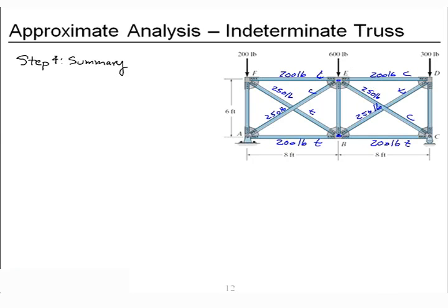My vertical members, we had 350 pounds, that's a 50, compression here at AF. 300 pounds compression here in member BE. 450 pounds compression here at member CD. So now we're ready for step 5. Let's go back and compare with our prediction.